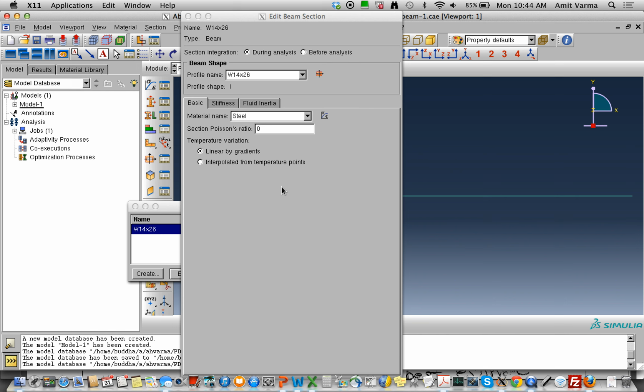So when you do this analysis using a finite element software, you're more often than not introducing option number 1 directly, which means that it will calculate the overall behavior and plasticity along the length and all of that, which means that you can't do much better than that. The only way you can improve upon this kind of a nonlinear analysis is to use a lot more finite elements along the length. Won't be able to improve much more on the analysis results that you get.